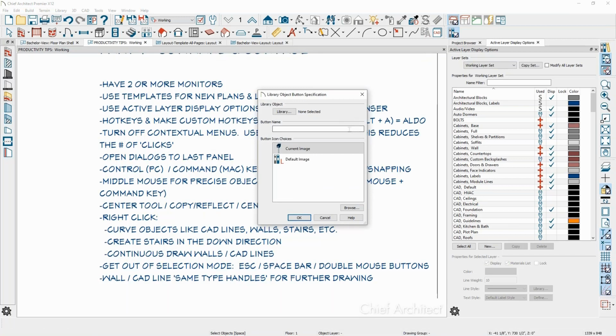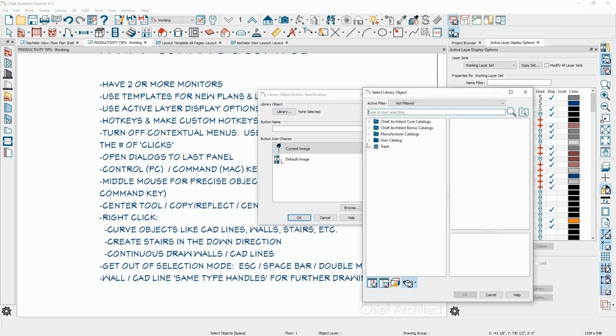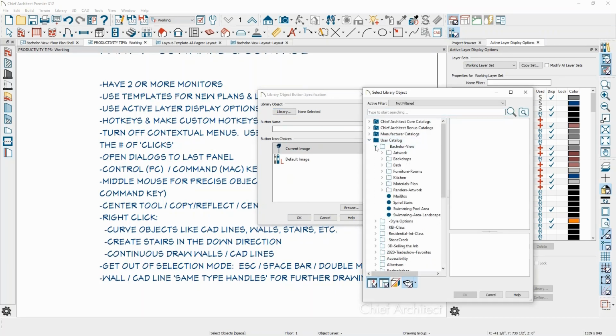Let's take a look. It's called Place Library Item. So type in the word place for search, LIB for library item. I'm going to pull that up onto my toolbar, place it up there. Let's close this. Now, when I click on this the first time, it's going to ask me what you'd like to map it to.